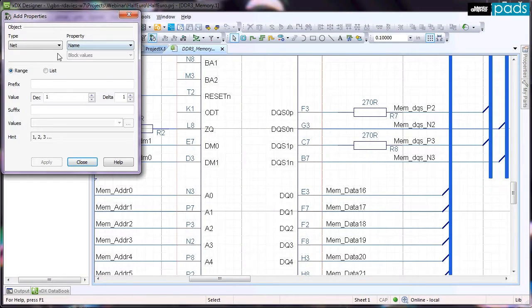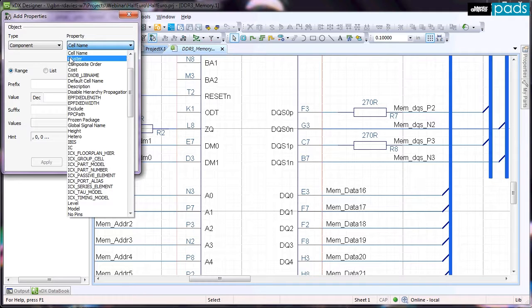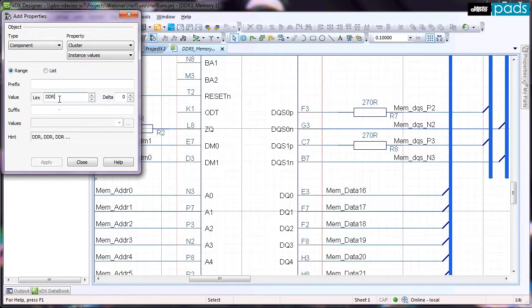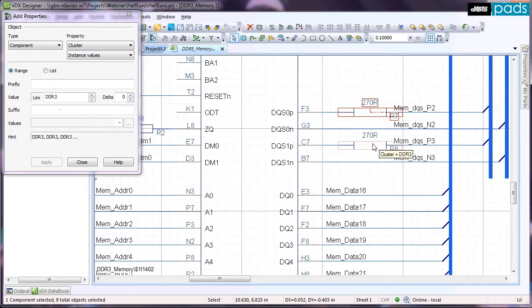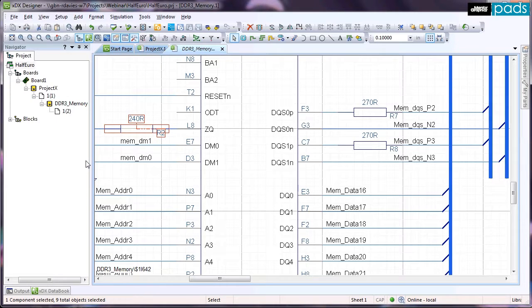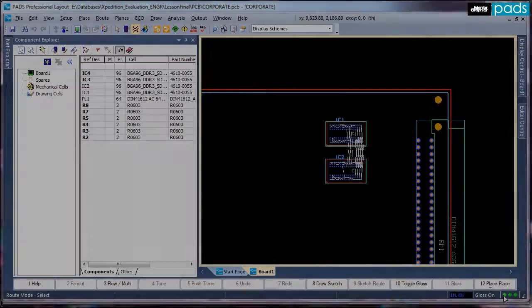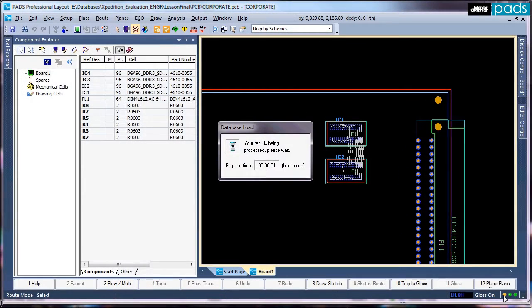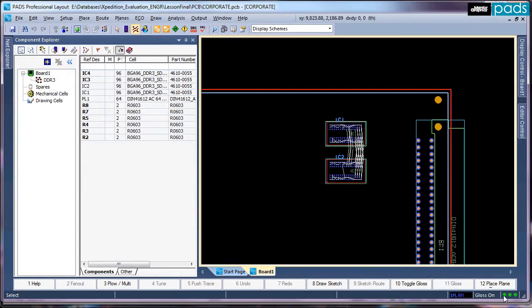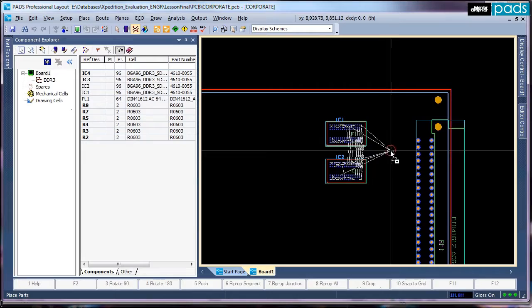Taking advantage of the PCB layout's hierarchical group planning, components may be grouped together in many different ways, such as by functional design or area. These groups and information can then be seamlessly passed from schematic through to layout, which then ensures that you're able to optimize the placement based on design intent. On forward annotation, the groups appear in the Component Explorer ready for placement, allowing you or the layout engineer to experiment with different arrangements and optimize the connectivity.